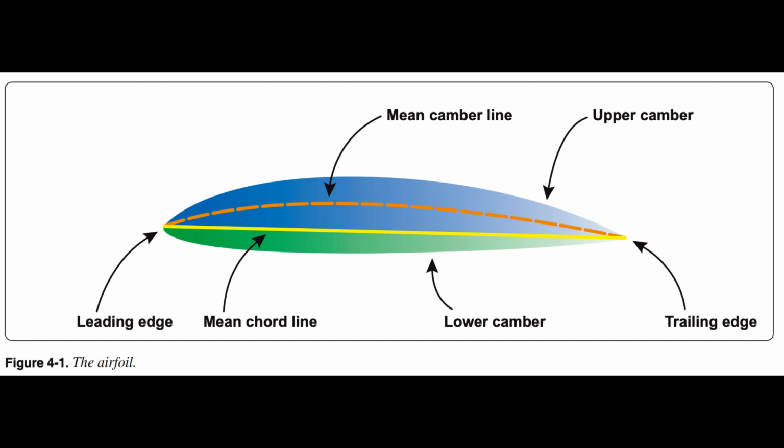The mean camber is a line located halfway between the upper and lower surfaces. Viewing the wing edgewise, the mean camber connects with the chord line at each end. The mean camber is important because it assists in determining aerodynamic qualities of an airfoil. The measurement of the maximum camber, inclusive of both the displacement of the mean camber line and its linear measurement from the end of the chord line, provide properties useful in evaluating airfoils.